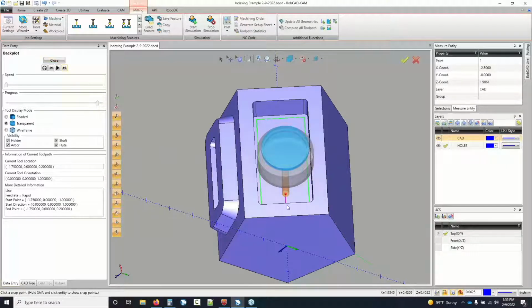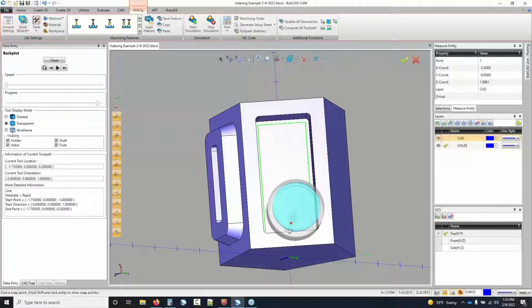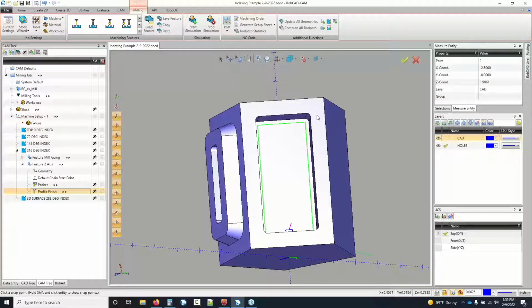And the benefit for me and why I like it a lot, since I started using it just literally like a week or 2 ago, is it doesn't lift up the tool. You know, normally the way we have to do spring passes is basically copy and paste the finish pass to run the finish pass over and over again. But that one will have the lead outs applied to it. So it'll lead in, make its cut, and lead out, lift the tool, and then plunge back down, lead in, make its cut, and lead back out.